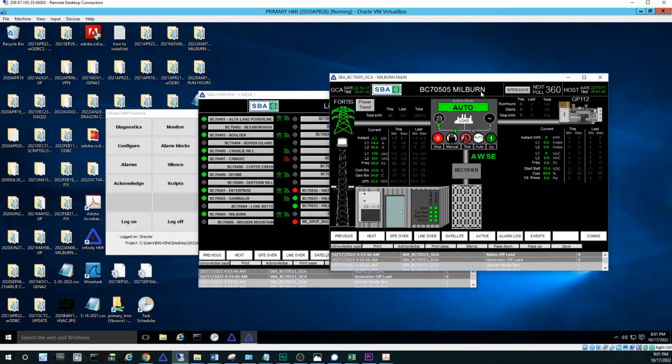We have a utility power indicator here, which is displayed as green when utility power is within specified parameters, and will turn red when any type of failure is sensed. This is metered at the transfer switch, and the transfer switch is actively keeping the utility power connected to the load as indicated here. In the event we had a utility power supply operating outside of normal limits, this indicator would go dark, the transfer switch would disengage the load as indicated here, and start the generator.